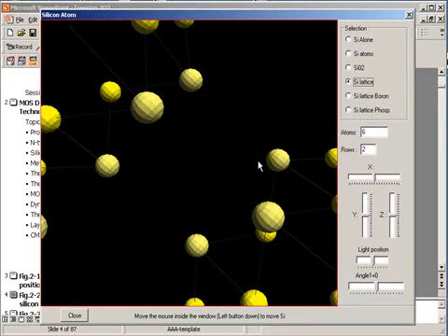The number of electrons which participate in the conduction is called the intrinsic carrier concentration. The concentration of the intrinsic carrier is known numerically, which I will not mention. The Sedra Smith textbook has the specifics of that. When the temperature increases, the intrinsic carrier density also increases. So the concentration of free electrons is assumed to be equal to the concentration of free holes.